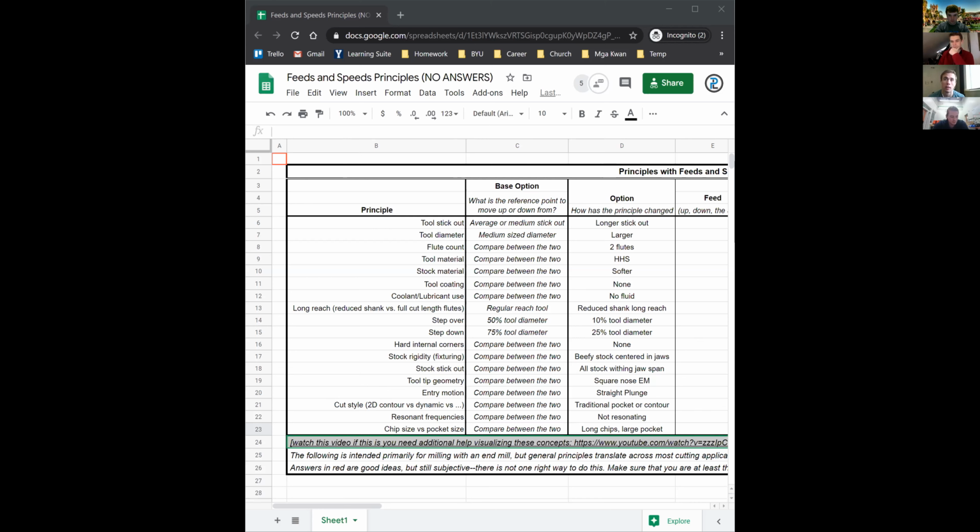So because of that, you want to wear out the other parts of the tool similarly to the tip. So if you use the full flute, great. Now in the case of end mills, using surface feet is really useful because then you can use the same surface feet for any diameter tool, and that'll give you the same finish, ideally.